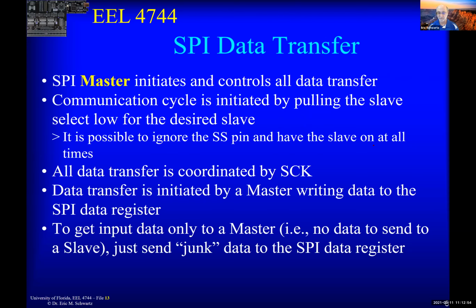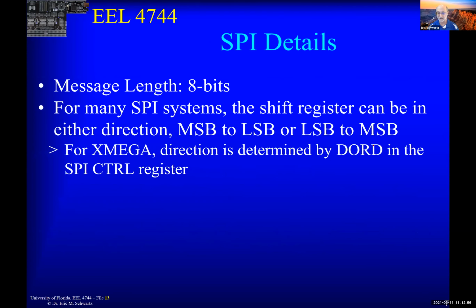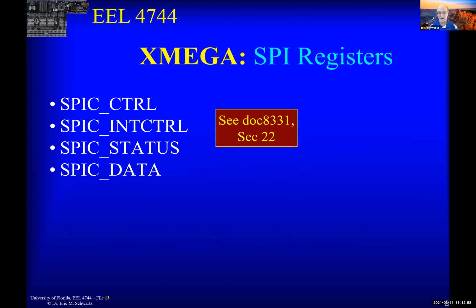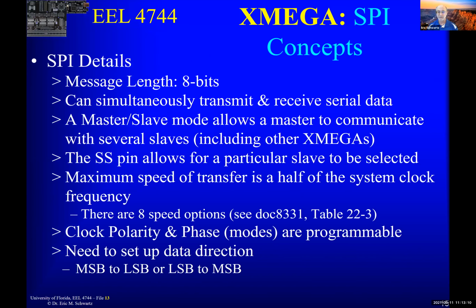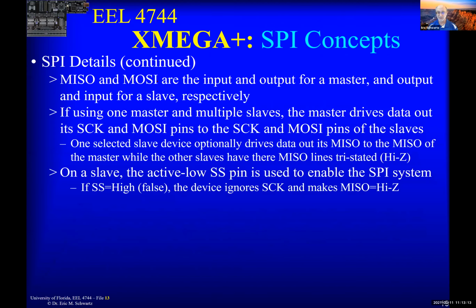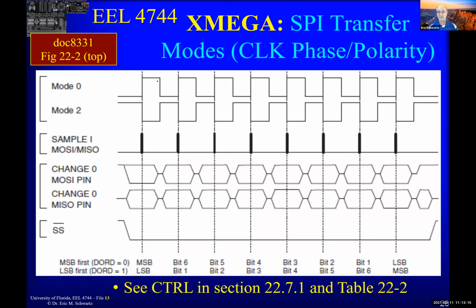Okay, so again, master initiates, lots of words here that they went over last night or whenever you watched that video. So these are the registers we have to deal with, the configuration registers for the SPI. Okay, so the phase and polarity, which is what Motorola called it. Motorola, I think, started this SPI.